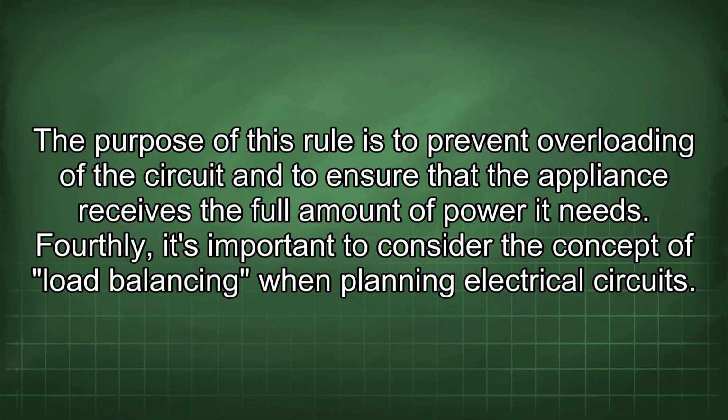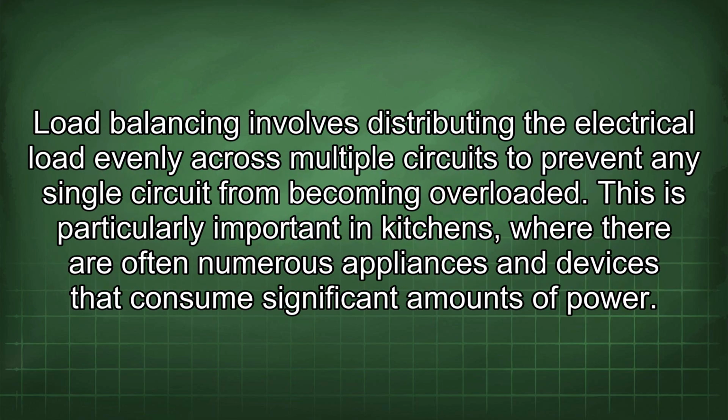Fourthly, it's important to consider the concept of load balancing when planning electrical circuits. Load balancing involves distributing the electrical load evenly across multiple circuits to prevent any single circuit from becoming overloaded. This is particularly important in kitchens, where there are often numerous appliances and devices that consume significant amounts of power.